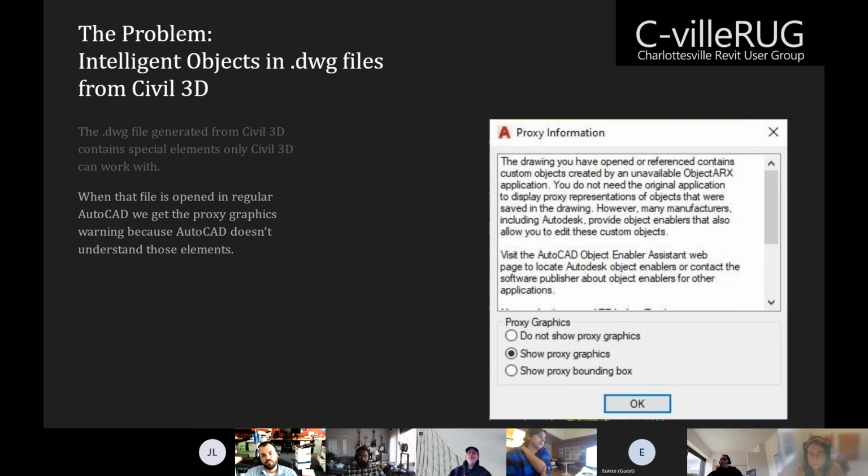So what I often will do is I'll select everything in an AutoCAD file, and I'll use Quick Select to get the list of all the element types that are part of that selection. And then once I see that list, often they will be listed like AutoCAD proxy, or sometimes there will even be elements in there that you'll be able to recognize as not being typical plain AutoCAD. So like points are often bad, so I always delete points because we don't really need them.